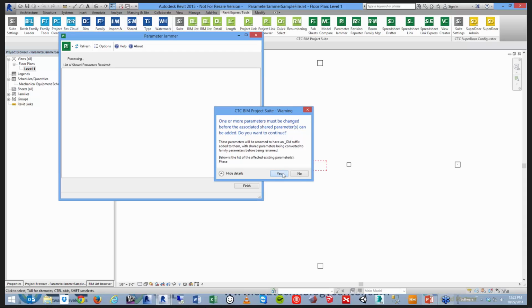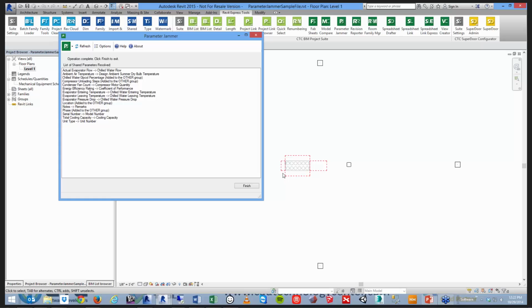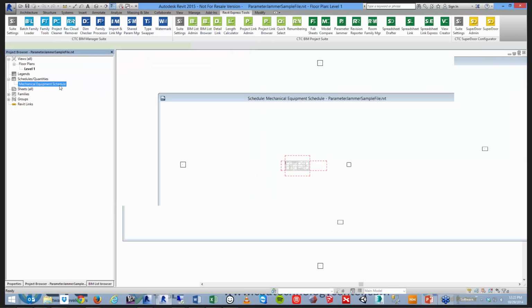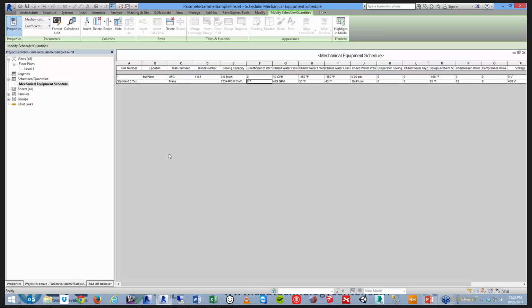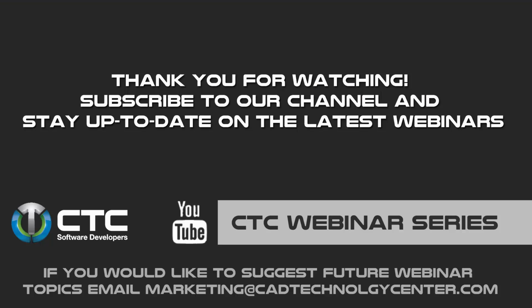So I'm just going to go ahead and say yes to this. I want you to continue. And it's going to process all of these. It'll just tell you what it did here. It's going to tell you what it's added and what it's changed. And when I click Finish and go back to the schedule, you can see that this guy is now completely ready to appear on this schedule. So I've mapped everything. It's now ready to receive data. And this was, again, the whole idea, is just to get the correct shared parameters into the family so that the family can work properly with your schedule.